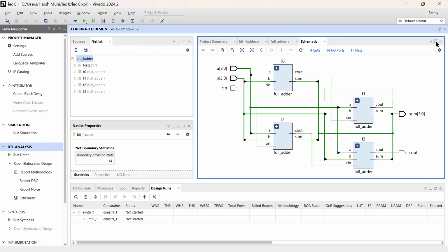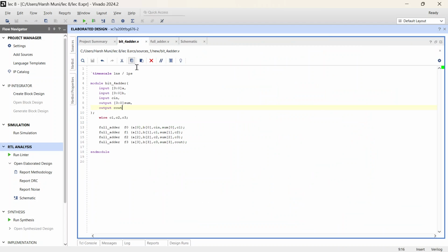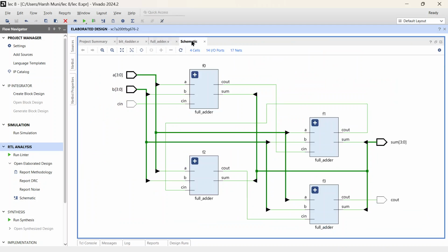Here it is. So as I said, using multiple full adders, for the input bit F0, it is transferring to F1, then it is transferring to F2, and you can see the C out here is acting as an input C in here. Here C out is acting as a C in for the third one.